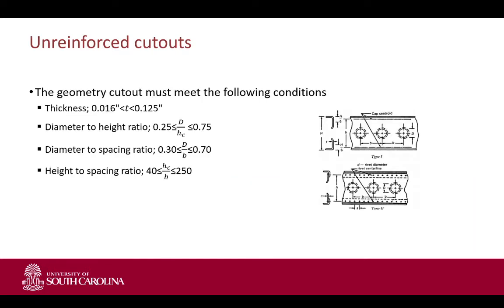And of course, you basically go through a checklist of all the different things that can play a role. The hole diameter plays a role, and the height of the total spar, because the hole cannot exceed a certain ratio. It's empirical data: you look at different graphs that have been developed over the years, and you check where your design falls within those graphs.